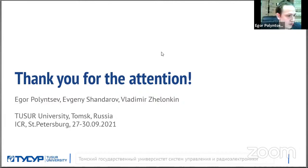And about few resources, you are quite right, because Raspberry is very short of resources. All processing is done very slowly, and it should be optimized for Raspberry Pi. We use a short vocabulary, about 50 words in our apps, and each app has its own vocabulary, again for optimization. So, for example, if you launch the riddles robot app, the special vocabulary of about 50 words is loaded, and the speech module can detect only these 50 words, again with quite low accuracy. So limitations are quite high, but we can detect video, process speech, and so on. It is not as perfect as it would be on a personal computer, but for Raspberry it's not so bad, though it could be better.